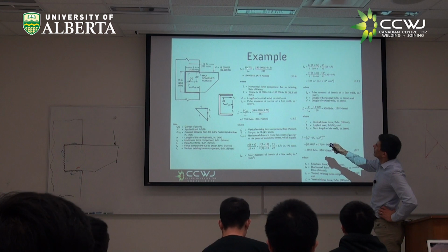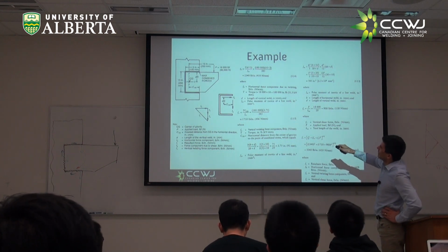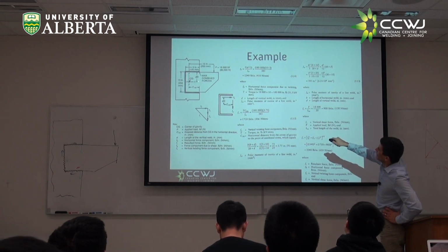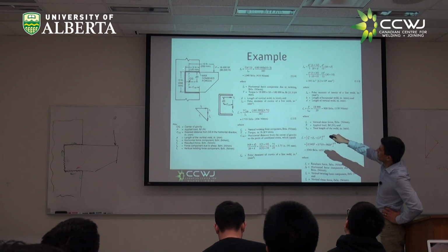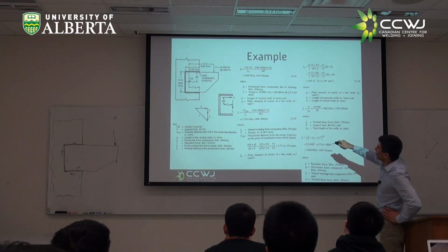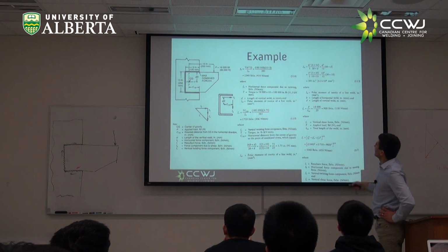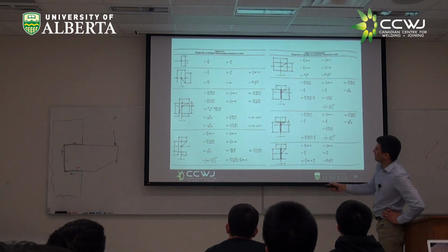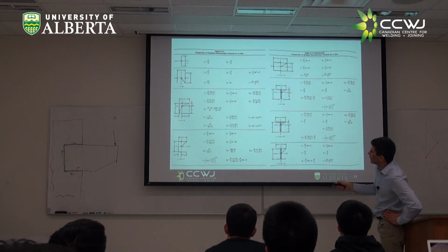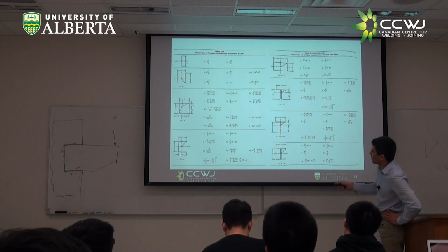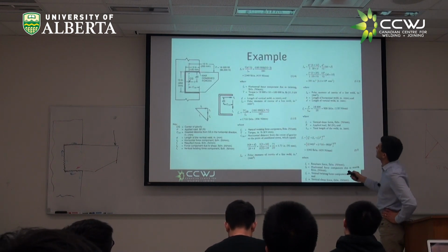So we have torque, the distance to the neutral axis, which in this case, for the horizontal force, is d/2, and the polar moment of inertia. And where does the polar moment of inertia come from? It comes from this formula we have here, this JW. That is this big chunk of formula we have here, right?